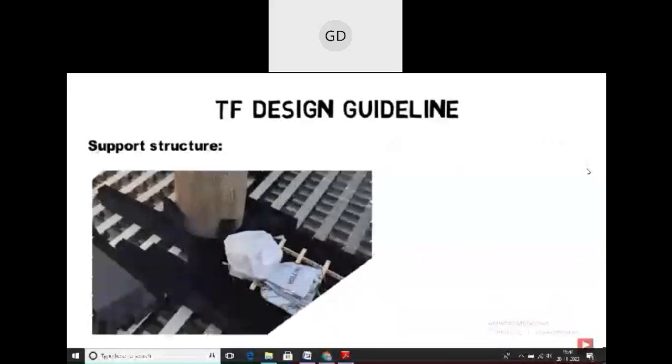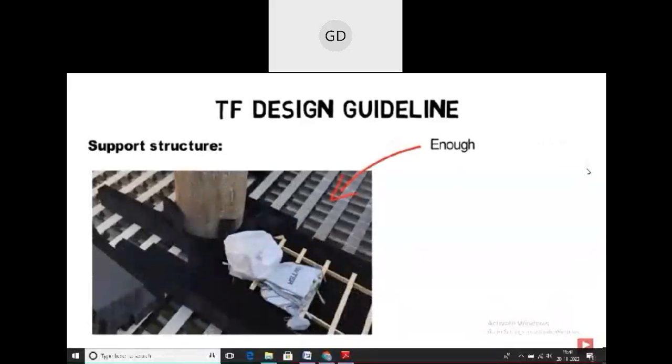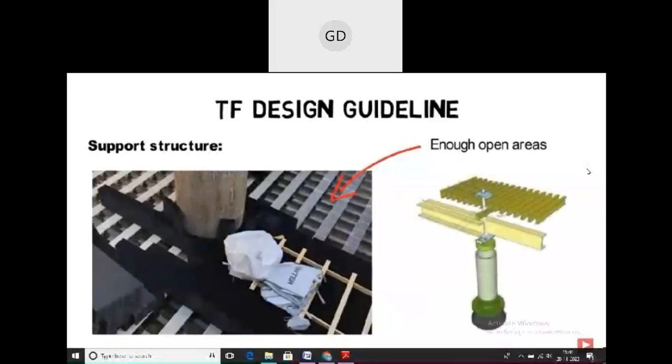At the same time, the supporting structure must leave enough space for sludge collection and removal and to avoid blockage of plastic film media channels. Therefore, the support structure typically consists of PVC stanchions, FRP grating and slope corrector plates to adjust for bottom slopes.